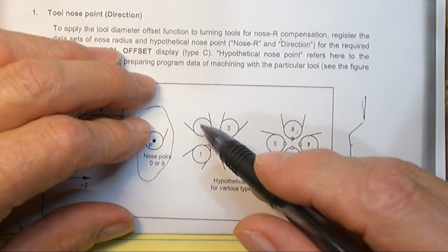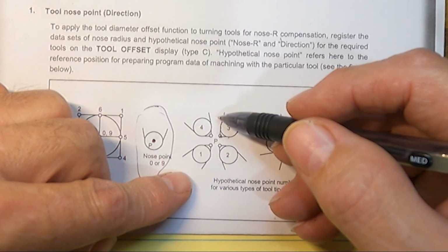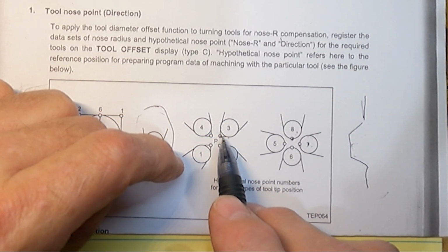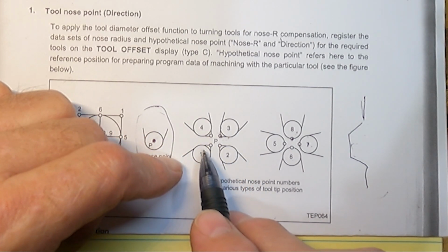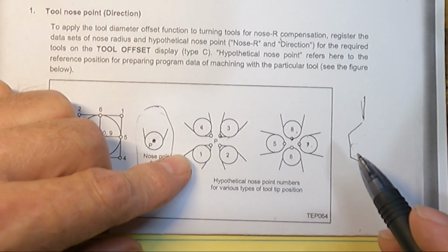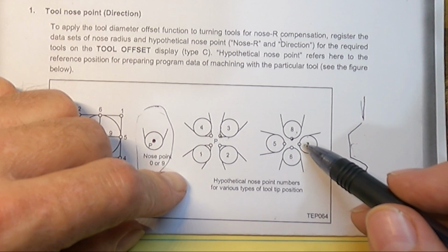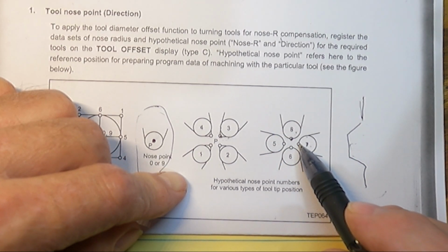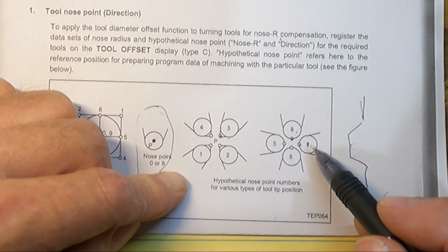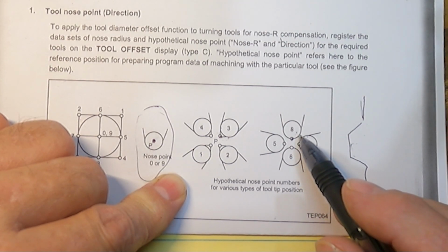So these are the normal directions, and you could see that the way you touch a tool off, you would touch it off either on your tool setter, or you would take a cut in the Z and set that offset, then you would take a cut in X and mic the diameter and set that offset here. And this is the normal turning directions for OD turning, ID back turning, and an OD back turning. And these are the numbers that you would set in your offset page. For straight in offsets like these, you would set these numbers, and you'd have to touch the tool off on the end of the insert, and then you'd have to set your offset such that it was on the center of the radius. On these, kind of like half of what the 9 or 0 is. So it would be centered, but on the end.